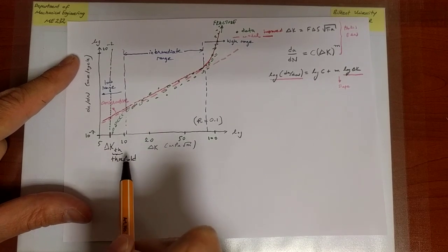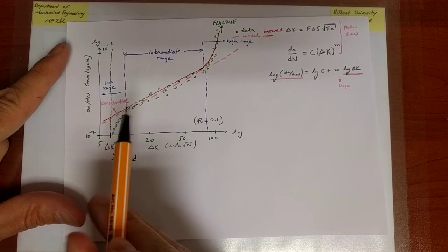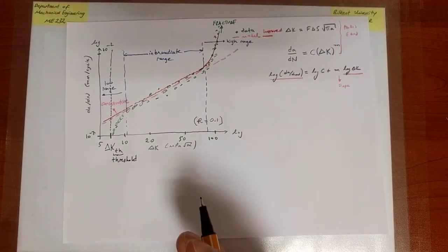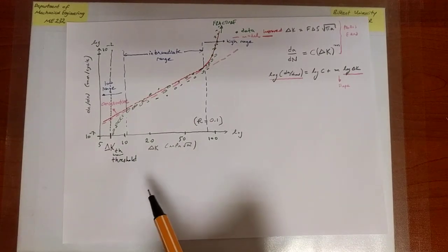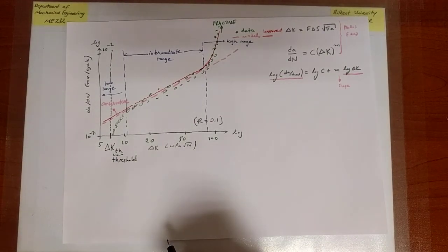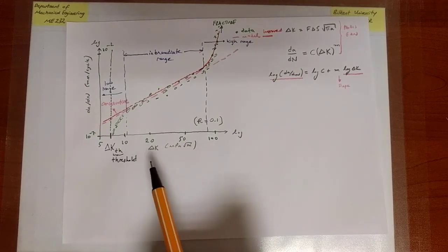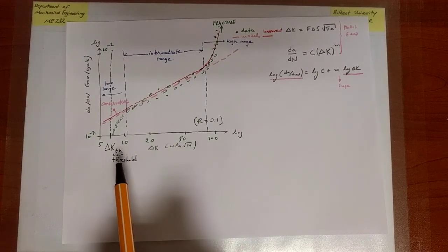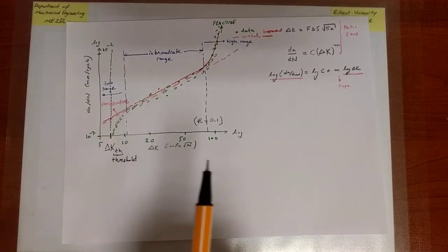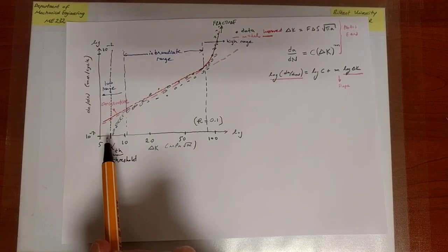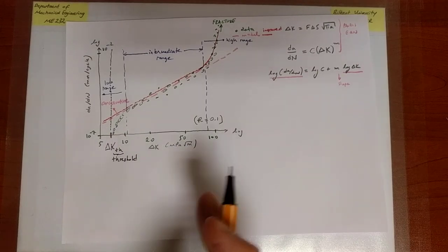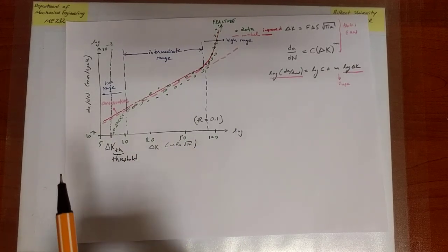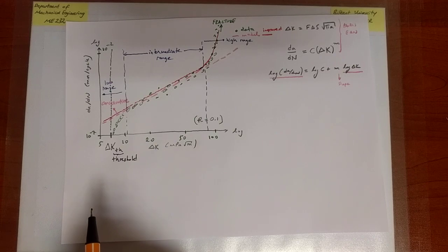So that is also a very interesting piece of information that comes from the monitoring of a single crack, because eventually we are going to see, when we look at the more complicated case of fatigue, high cycle fatigue in particular, that there are certain materials, in particular aluminum, to which if you impose a stress range that is smaller than a certain value, it will not fatigue. You can cycle it back and forth forever, and that is actually a key piece of design information.